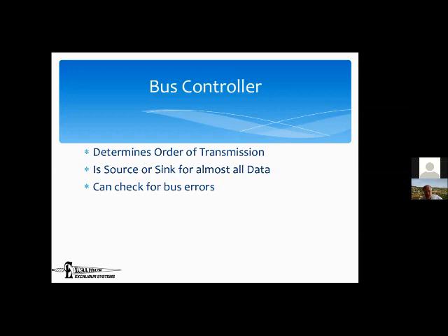And that brings up the problem of, if you now were sharing a wire as opposed to 429 where everybody had their own wire, how do I share a wire and still not allow data to crash into each other? And this is one of the central issues that all networks have to deal with. And the way 1553 deals with it is through the bus controller. The bus controller decides who's going to speak at any given time. Now, there are certain side effects to this.